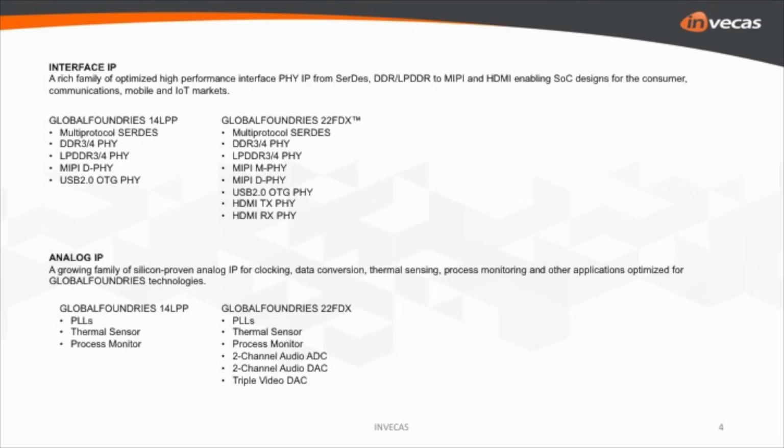Again, these portfolios are spread across the GlobalFoundries 14LPP, having multi-protocol SerDes, DDR3/4 PHYs, LPDDR3/4 PHY, the MIPI D5, and the USB 2 OTG 5. On the GlobalFoundries 22FDX platform, our IP portfolio is comparatively larger, which has additional HDMI TX and RX 5 blocks, and the MIPI M5 as an extra IP on the 22FDX platform.